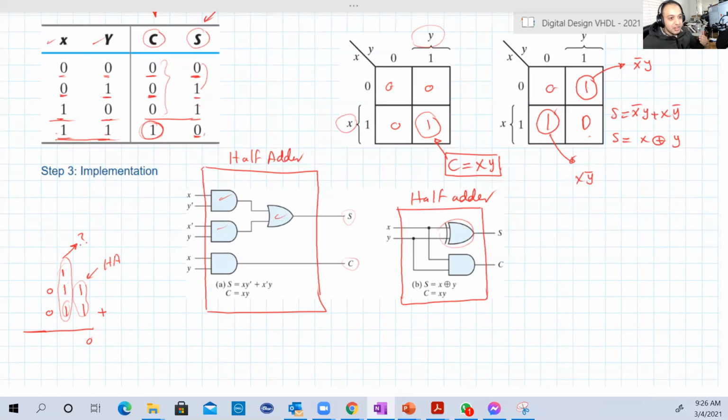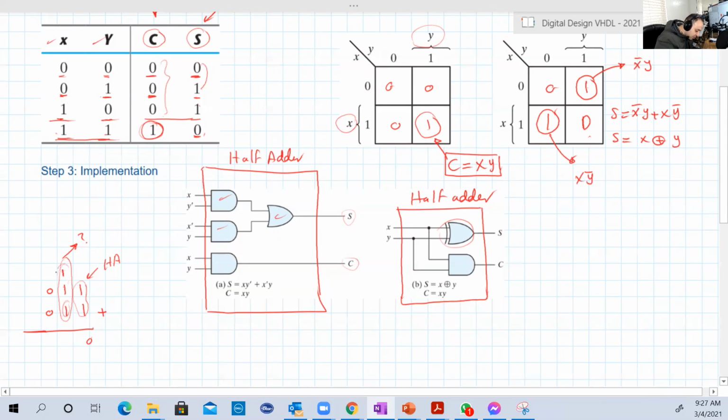Okay? So that's basically an introduction for our next circuit. Our next circuit is called full adder. Which can be summarized in the following sentence: design a circuit that adds 3 bits together. Okay, this is full adder. And once we do that design, we're gonna relate the full adder to half adder, because basically, let's look at the example again. So 1 and 1, you're gonna add these two first, then the result will be added to that guy, right? So again, you have 2 half adders.